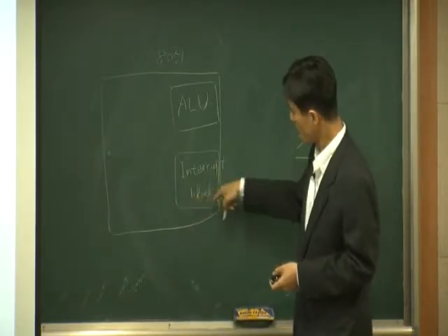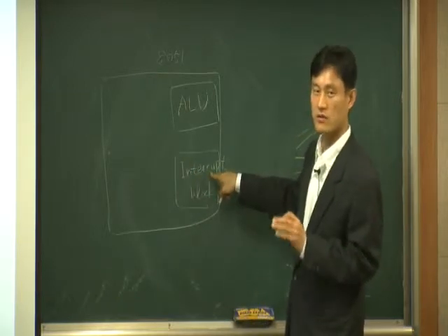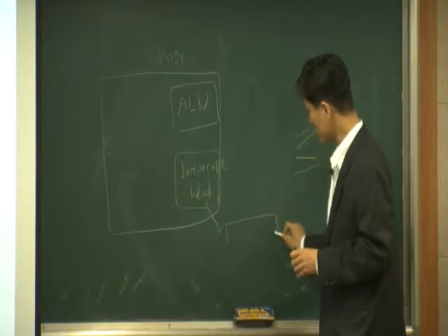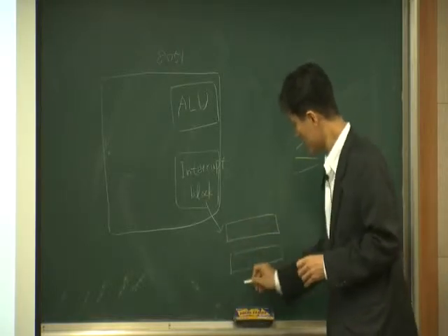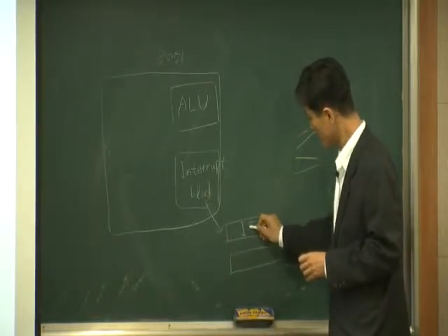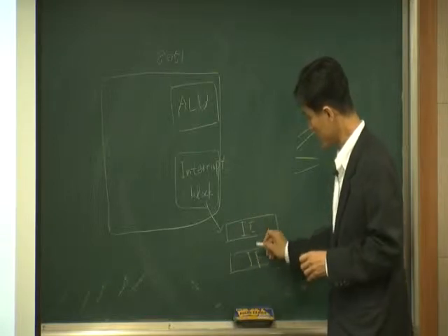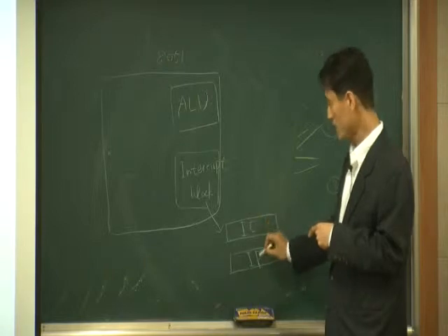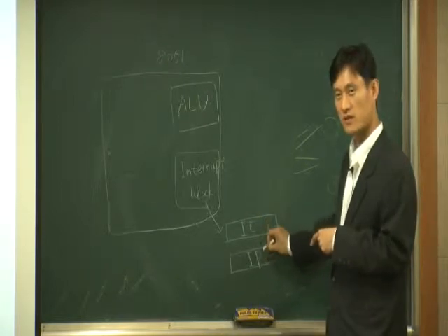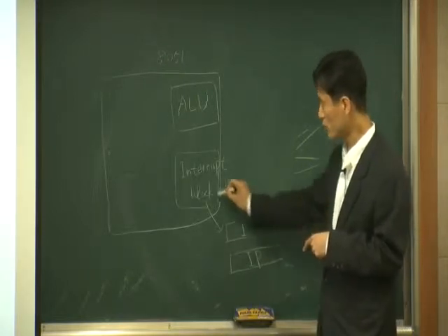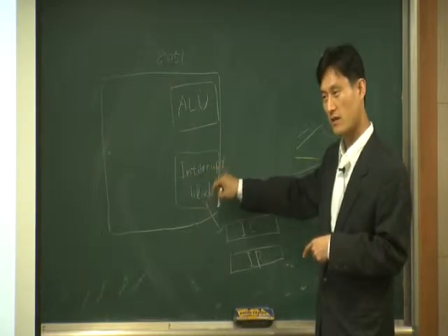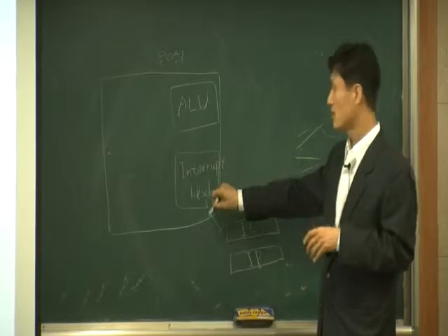So there is some hardware block which takes care of the interrupts. Inside of this hardware, we have registers called IE and IP. What is IE? Interrupt enable register, and interrupt priority register. These registers belong to this block, the interrupt block. Again, I'm talking about hardware, right?